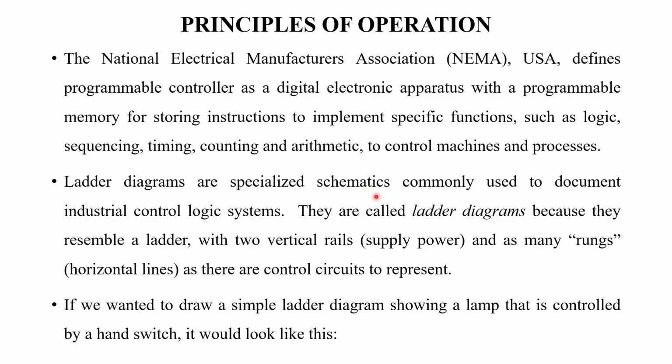The program is documented as industrial control logic using a ladder schematic or ladder diagram, which resembles a ladder with two vertical rails that represent the supply power, and many rungs, that is horizontal lines, which represent the control circuits. So it will be like this.